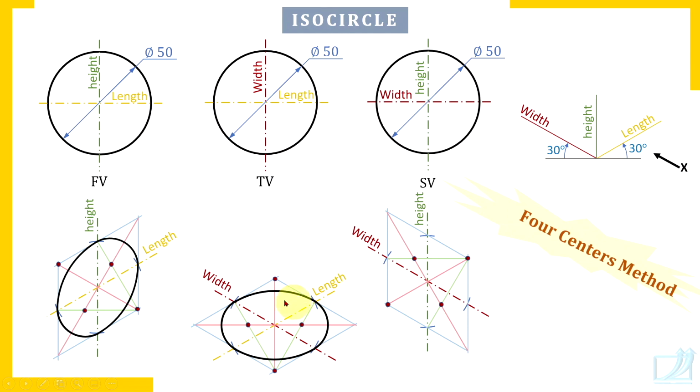Here it is in the top plane of the isometric view. Similarly, now here try to understand. Longer arcs with centers in diagonally opposite quadrants, and shorter arcs with centers in the same quadrant. And you are going to draw these arcs from midpoint to midpoint of the sides of this rhombus.